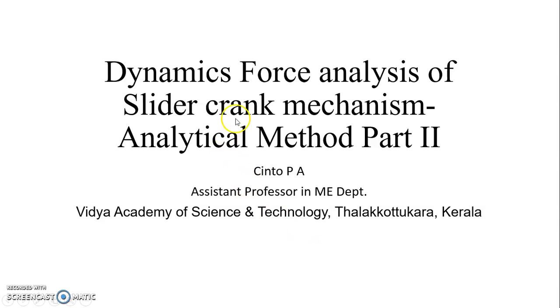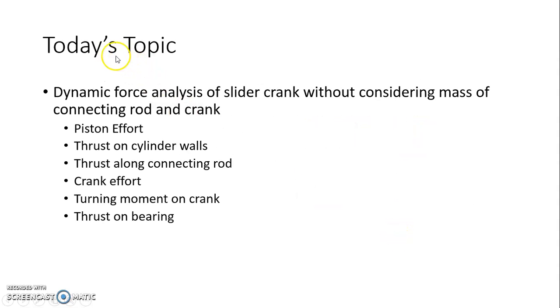Today's topic is Dynamic Force Analysis of Slider Crank Mechanism, Analytical Method Part 2. Today we are going to discuss the dynamic force analysis of slider crank without considering the mass of the connecting rod and crank. The terms related to the dynamic force analysis are piston effort, thrust on the cylinder walls, thrust along the connecting rod, crank effort, turning moment on the crank, and thrust on the bearing. Let us see what these terms are.